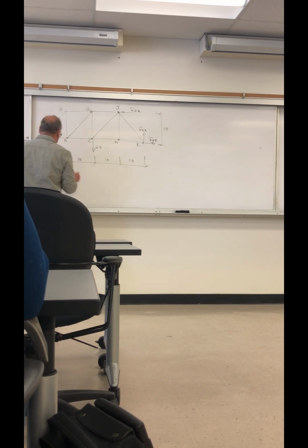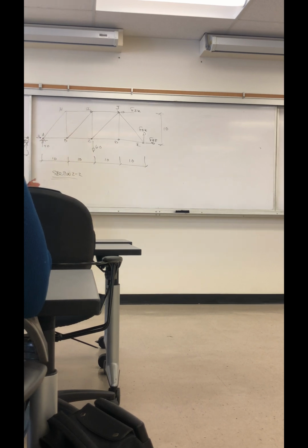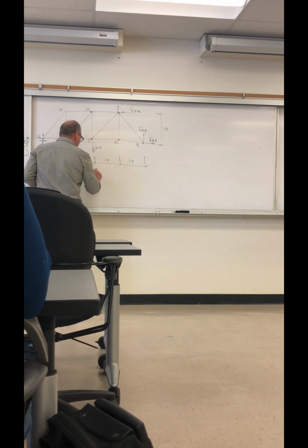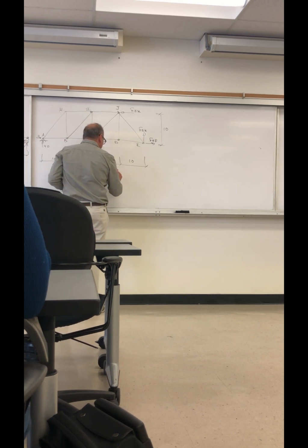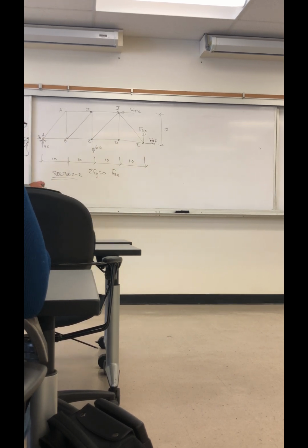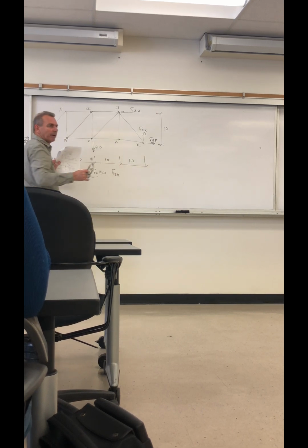So we'll start with section 2, with a summation of forces in the Y. That'll allow us to solve for F of EK. You have to be careful, because there's a 60 also, so it's not just the reaction like the last cut. We're summing the forces, doing the statics on this whole truss up to the cut from the left.